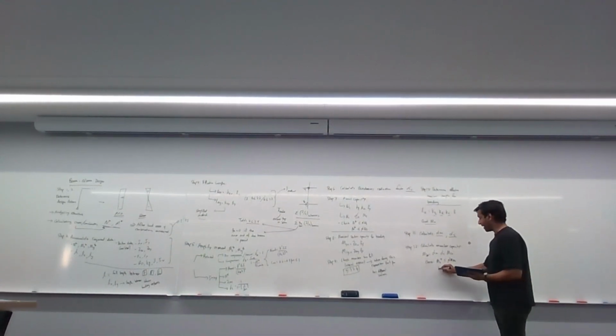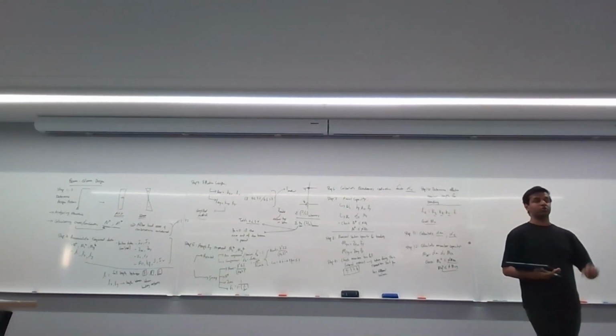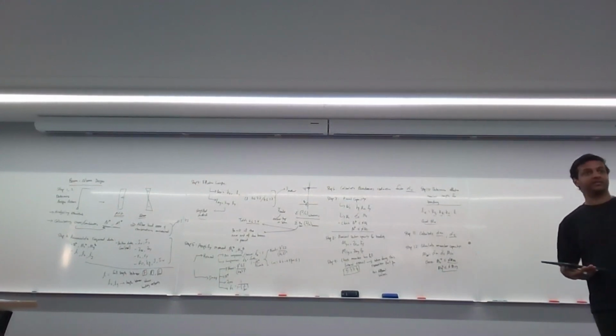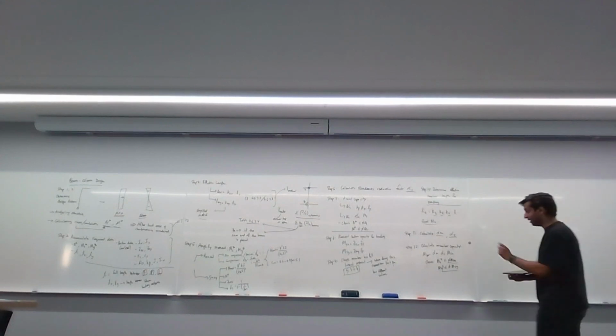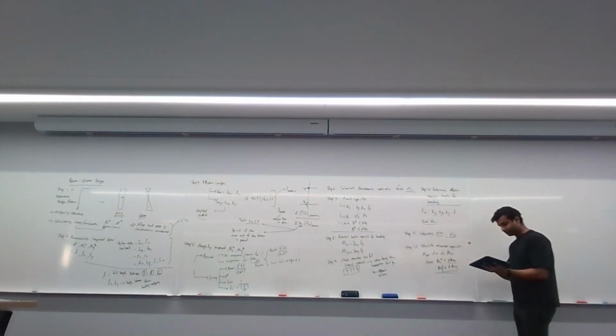Okay, but My star is checked against phi Msy. This is really important. Okay, you check against the member capacity in the x direction, but in the y direction you check it against the section capacity. Okay, really important thing to identify that this is what you're checking for.